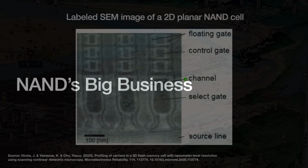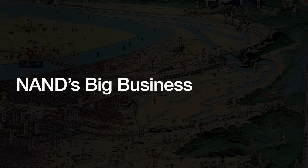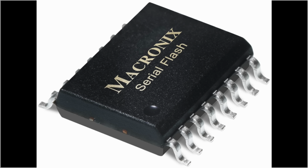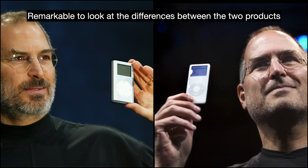When NAND first hit the market around 1995, a different architecture called NOR dominated. NOR has similar memory cells, but wires them together more like DRAM does, giving faster data access at the cost of lower density. Today, vendors use them to store crucial hardware boot code like BIOS. But NAND's more compressed architecture made it possible to create a solid-state mass storage product competitive with a hard disk drive. After Apple adopted NAND storage for its new iPods in 2005, the market took off and it eventually eclipsed NOR.